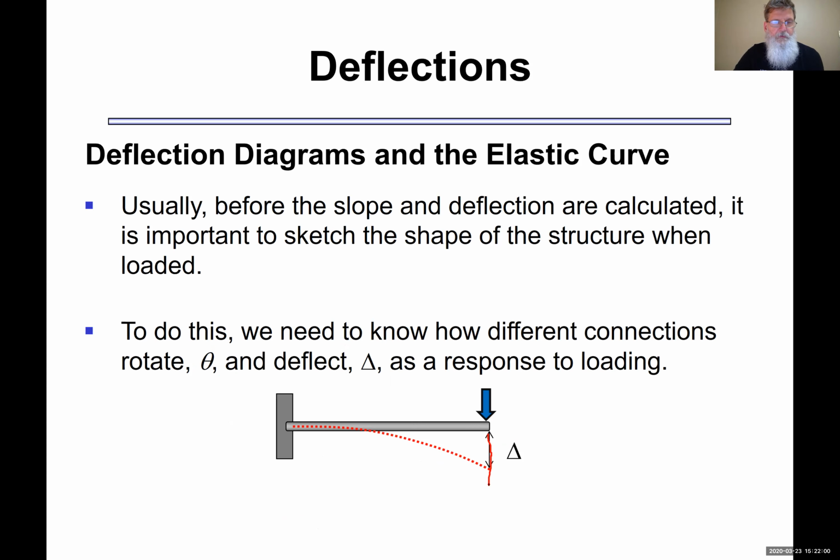And you'll notice over on the left side of the cantilever that I have not only no displacement, but what's unique about a fixed connection is also there is no rotation. So again, pins and rollers will have no displacement, some slope, something that we'll have to compute. A fixed connection will have no slope, no displacement, but everywhere else in the beam will have slope and displacement. So those will be conditions that we'll use later on when we do some problems.